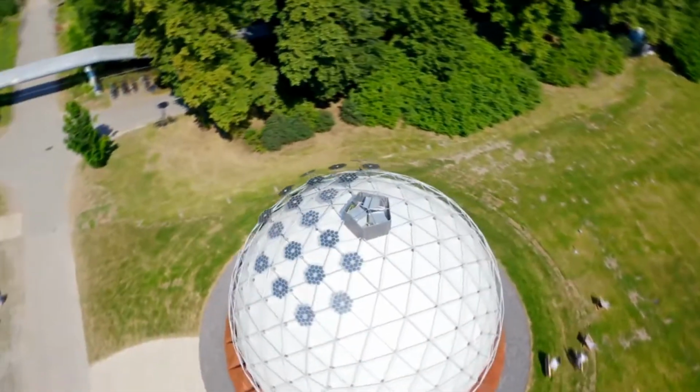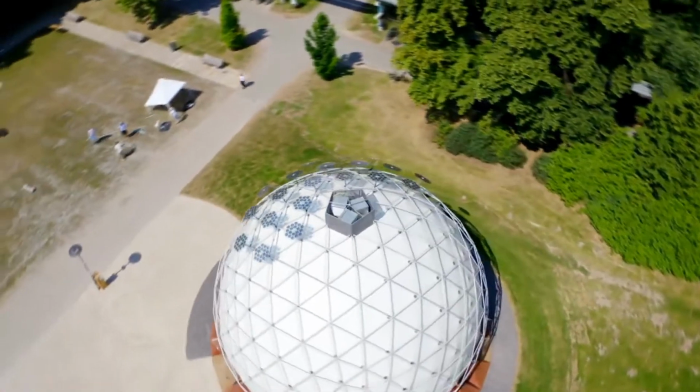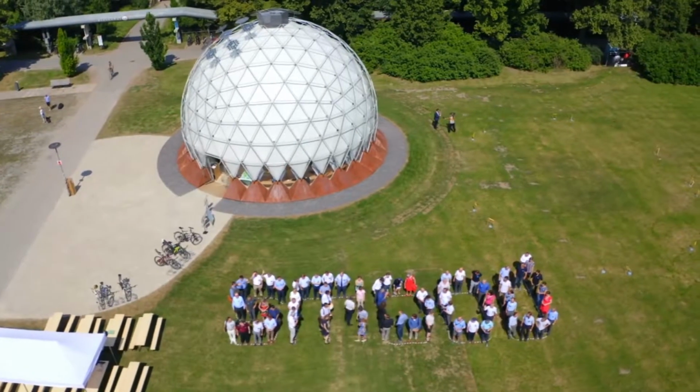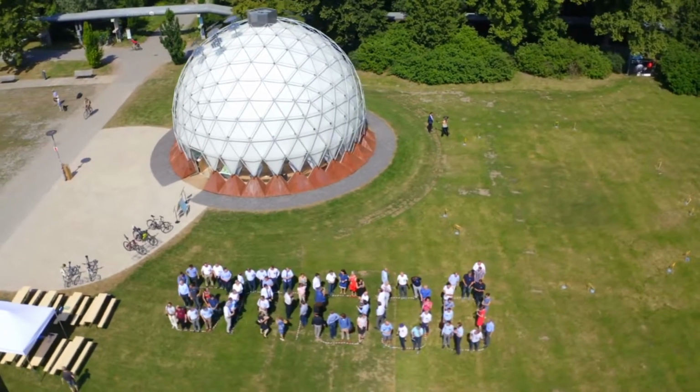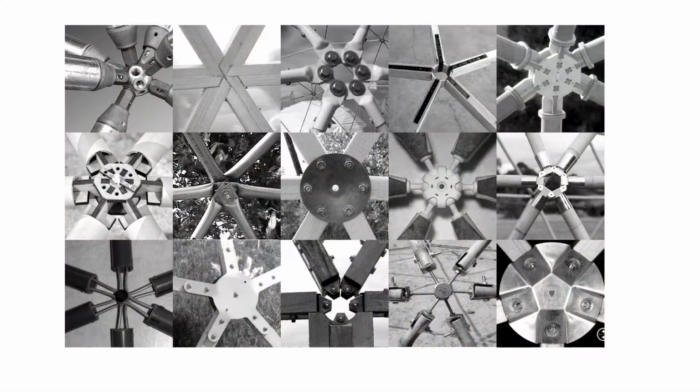Geodesic domes have their own special advantages, such as extremely high load-bearing abilities, but also the typical disadvantages of such type of prefabricated systems: a large number of different connection joints. An industrial sphere-shaped connector was used in the case of the Klima pavilion. Often connectors should be developed by the architect individually, according to load-bearing requirements and assembly convenience.